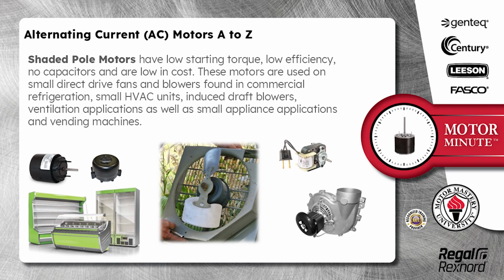Shaded pole motors have low starting torque, low efficiency, no capacitors, and are low in cost. These motors are used on small direct drive fans and blowers found in commercial refrigeration, small HVAC units, induced draft blowers, ventilation applications, as well as small appliance applications and vending machines.